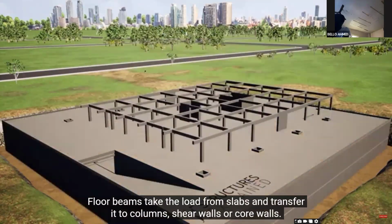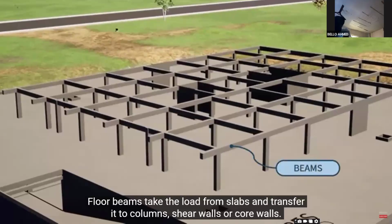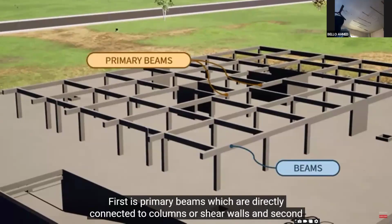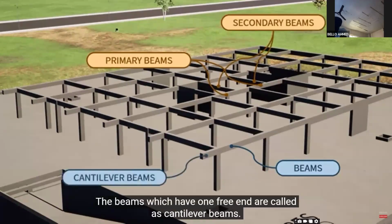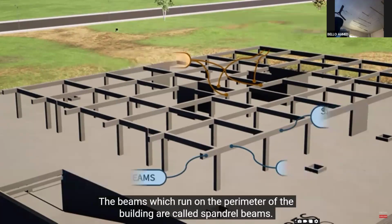Floor beams take the load from the slab and transfer it to the columns, shear walls, and core walls. Beams are basically of two types. First is primary beams, which are directly connected to the columns or shear walls, and second type is secondary beams, which are connected to the primary beams and transfer load from slab to the primary beams. The beams which have one end free are called cantilever beams. The beams which run on the perimeter of the building are called spandrel beams.